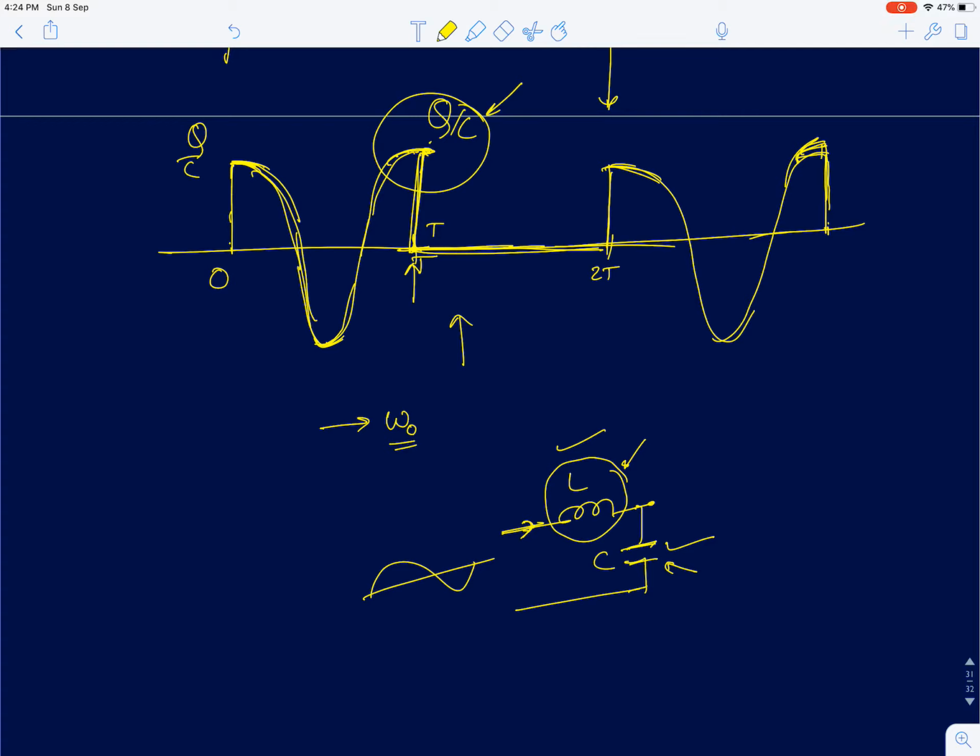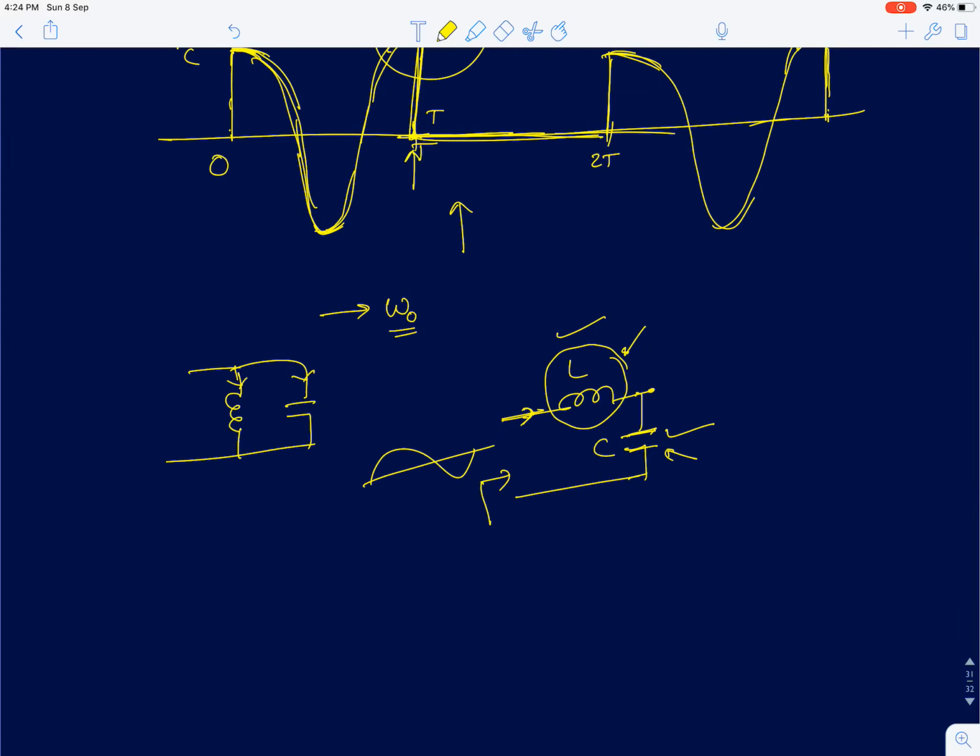I'm not writing exact equations for it, but I've derived the equation to find the voltage across a parallel tank. From that, for a parallel tank I computed the voltage across the tank, and from that we can easily compute the currents through the inductor and capacitor. So everything in this circuit is known. Similarly, for a series LC circuit, I can easily compute by a similar procedure.